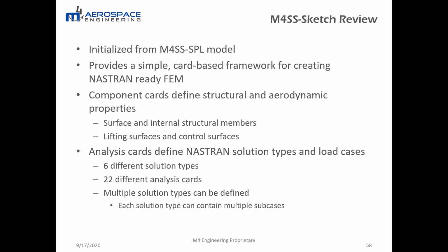So to summarize, the sketch model is initialized from the sketch point layout model, which places sketch points on OpenVSP components. Sketch provides a simple card-based framework for creating Nastran-ready finite element models.